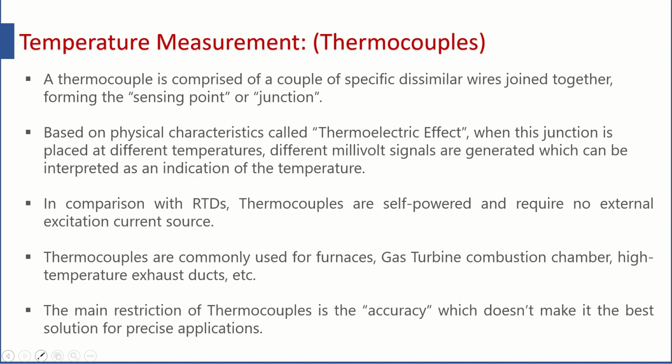Now you may ask me one question, whether we can take any metal. Yes, you can take any metal, but whether it will be giving you a detectable output or not depends on the characteristics of the metal. So therefore in industry there are standards which are used, and you will find the thermocouples commercially available as J-type thermocouple, K-type thermocouple, like that.